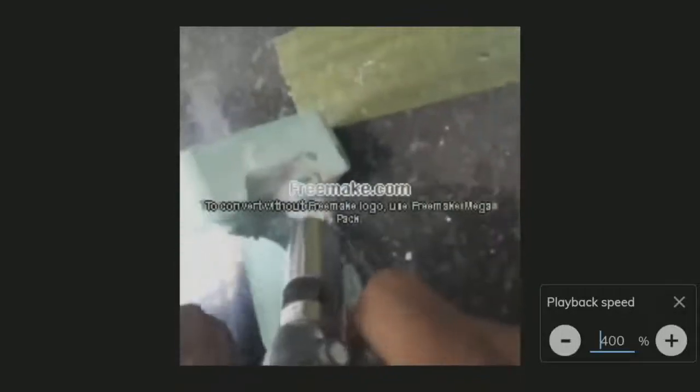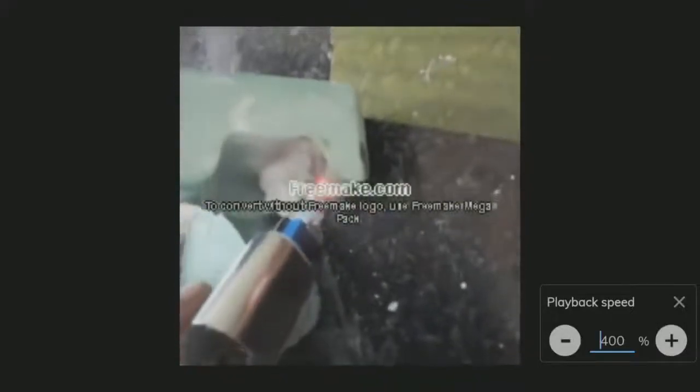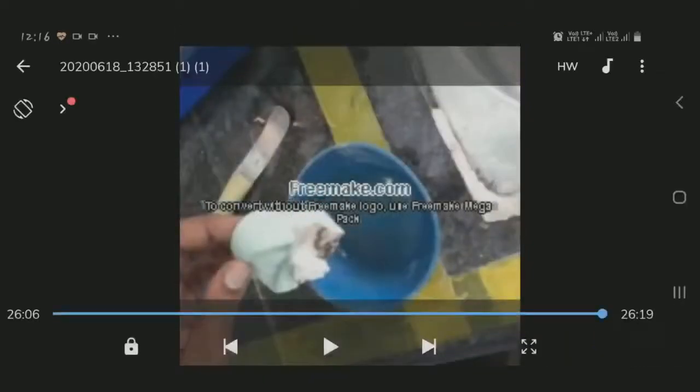Yes, that has been done. And now coming to the soldering process. So this is the application of flux which you are seeing now. After application of flux, you should heat up the flux a little. Take the silver solder and place it in that area. Heat the silver solder along with the flux. Since the flux is there, the silver solder flows into the area where you require soldering to happen. So when the soldering is done on both sides of the loop, quenching is done.